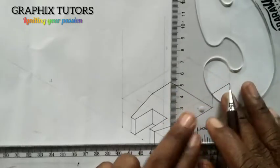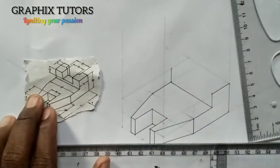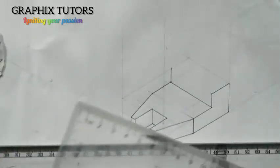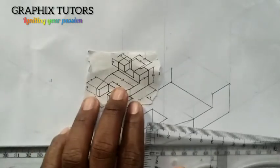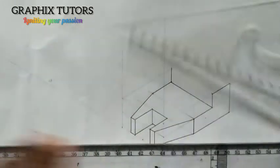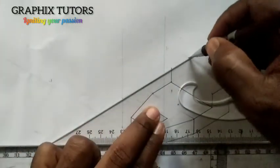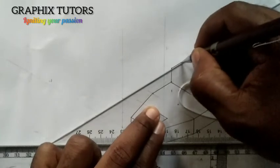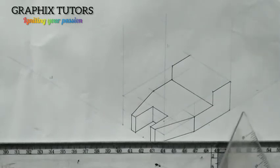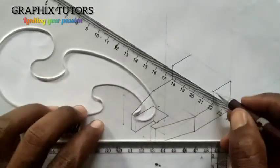Why am I taking it up? Because this guy here also is going up. Now I will just take my meter rule with faint line, since I'm not really sure. But one thing I'm sure about is that just like here is touching here, here also is touching here. So I'll just use my meter rule with the help of my T-square and Z-square. I'm going to join these two. You must use your Z-square and your T-square simultaneously for you to enjoy the process. Now if I have this way, I'll just use my faint line and join these 2 points together here.